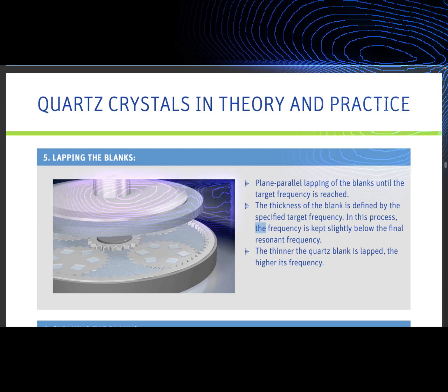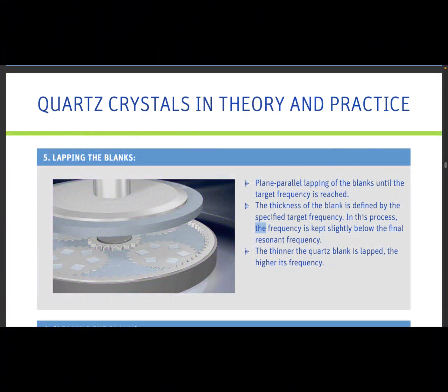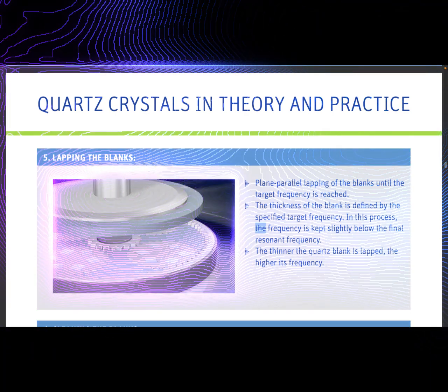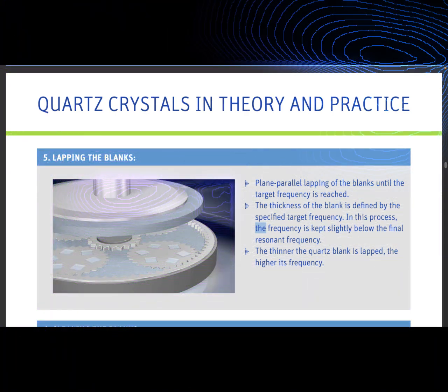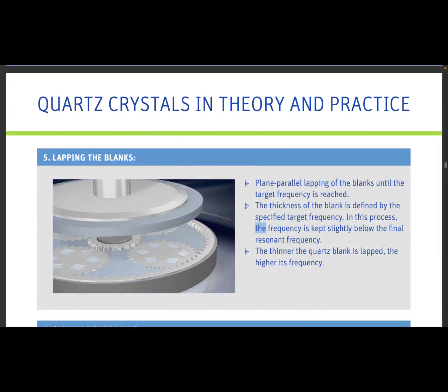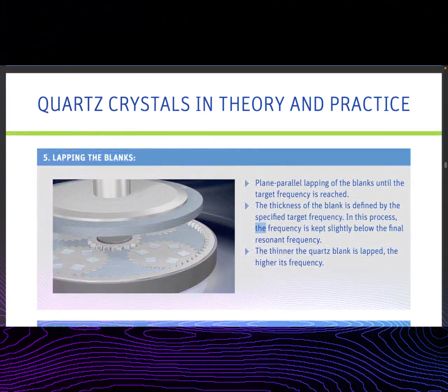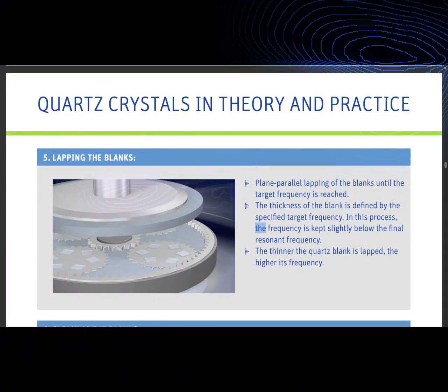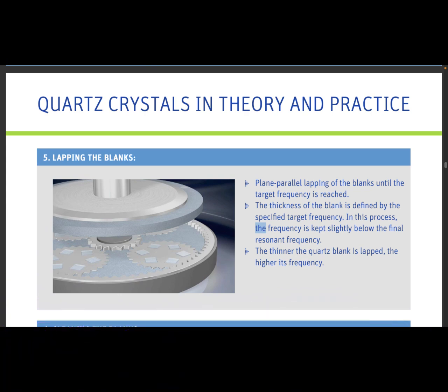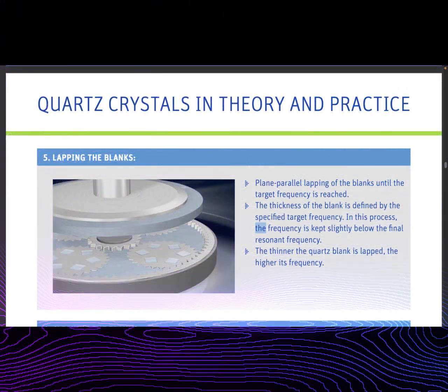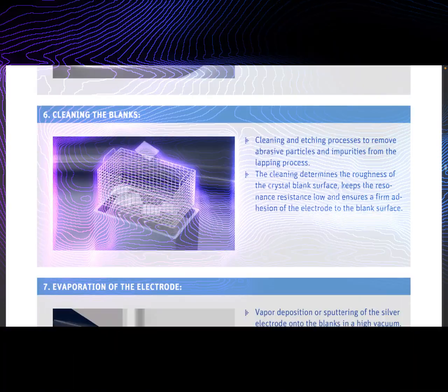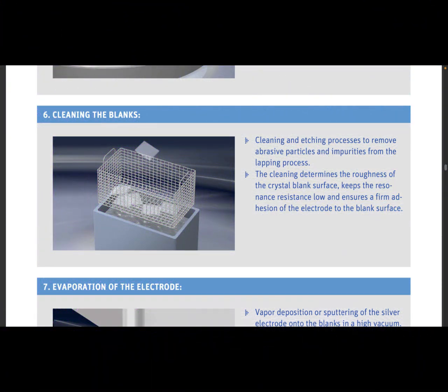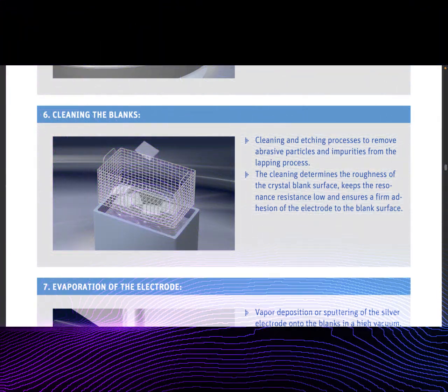More accurate crystals are more expensive. Jitter. The short-term stability of the oscillator frequency. Excessive jitter can interfere with communication protocols and cause an increased bit error rate. Stability. How the frequency of the crystal changes with temperature and aging. The cut known as AT minimizes the variation around normal ambient temperature.